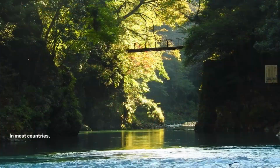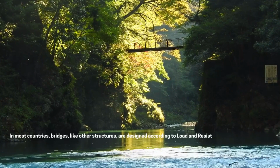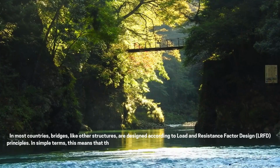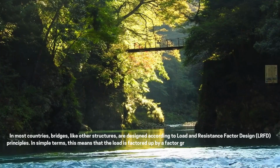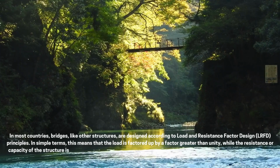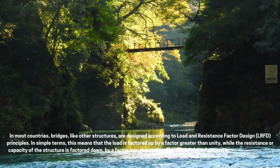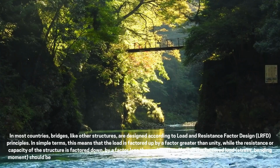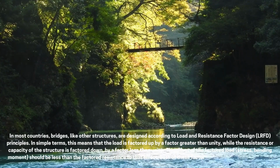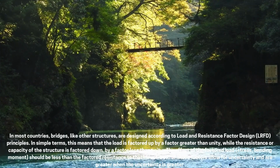In most countries, bridges, like other structures, are designed according to load and resistance factor design (LRFD) principles. In simple terms, this means that the load is factored up by a factor greater than unity, while the resistance or capacity of the structure is factored down by a factor less than unity. The effect of the factored load, stress, bending moment, should be less than the factored resistance to that effect. Both of these factors allow for uncertainty and are greater when the uncertainty is greater.